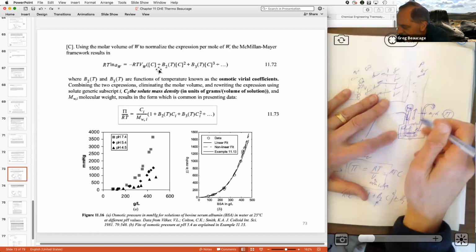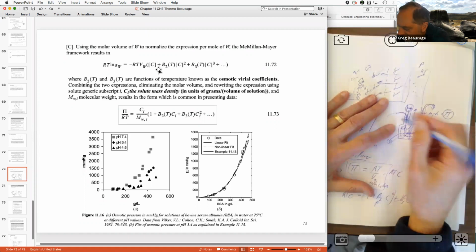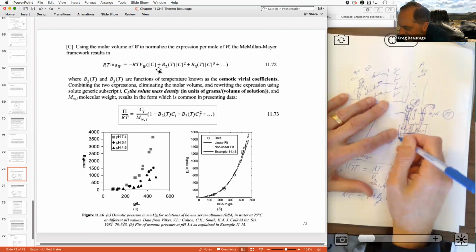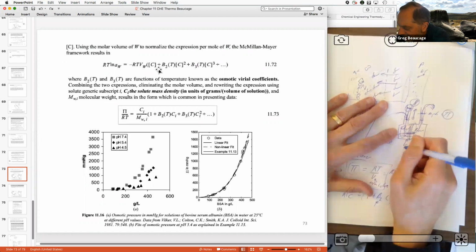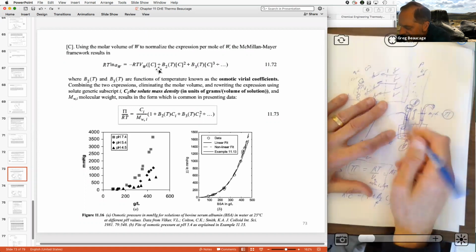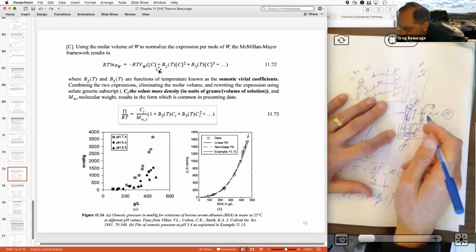And then eventually something else will build up on the membrane that clogs it. Then you have to replace the membrane. So the costs are the pump, right? The flushing operation and then replacing the membrane. Those are the expenses of this. And there's a pressure system that you have to set up. The pressures aren't huge, but it's enough to just get this to go, right?